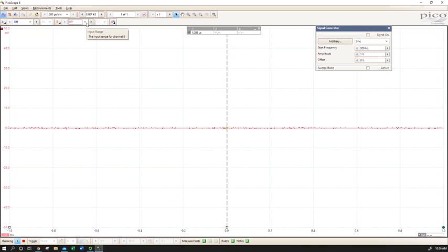So I'm positioning it on my protoboard, and I already know that a different capacitor allows me to visualize resonance differently on this. So I'm going to go ahead and put the primary coil of that little audio transformer in series with a 4.7 nanofarad. So I'm stepping my capacitance down by a factor of 10. And that actually is going to give me a little bit clearer view of resonance there. But otherwise, same thing. The primary coil of my audio transformer is now in series with a 4.7 nanofarad capacitor. I'm using the same resistor, and they're all together in series.